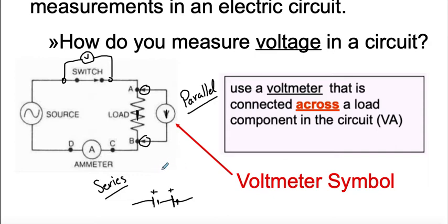So if I had a 2 volt and 2 volt battery hooked together in parallel, remember that looks like positive to positive and negative to negative with batteries, then that's not going to give me any voltage. I wouldn't measure the amps in the system either. So you want ammeters hooked up in series and voltmeters hooked up in parallel in order to get readings accurately.